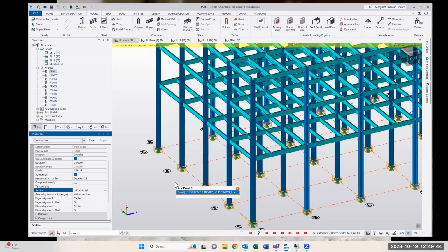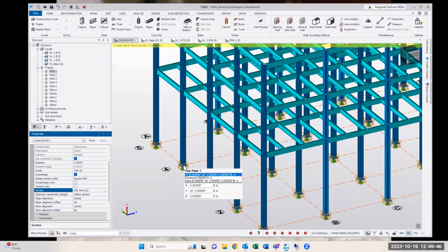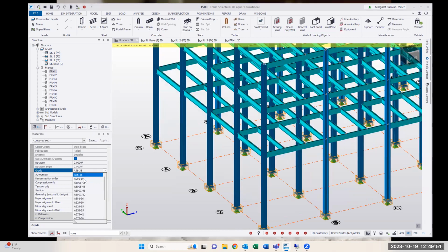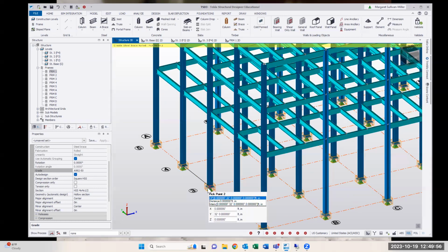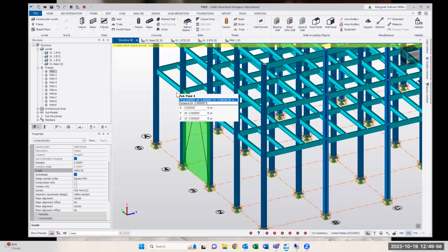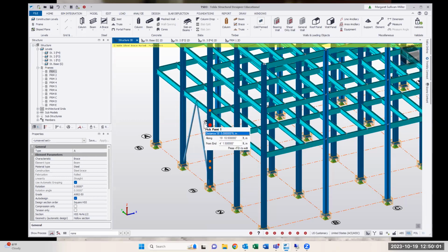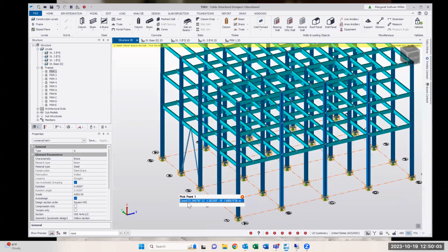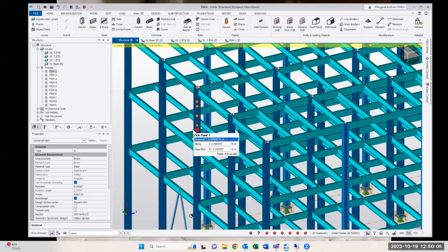So the way you do this is I've selected my section properties. I've got my correct steel, let's say A992-50. So I'm literally drawing a box where I want my brace to be, right here. In Tekla Structural Designer, when you draw braces, you literally draw pairs of braces. It's not going to analyze correctly if you try to draw a singular brace and then a singular brace. And you kind of want to do this with each level, right?